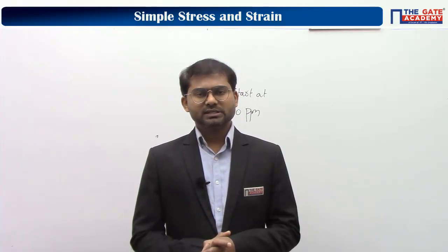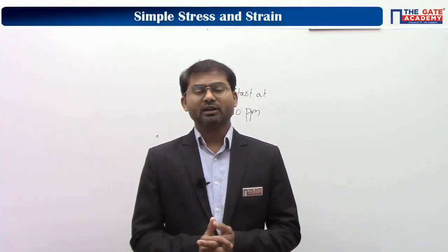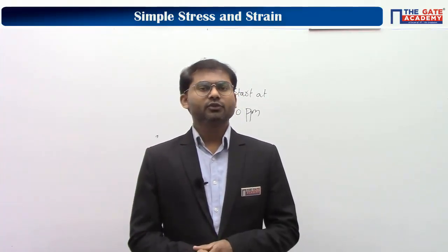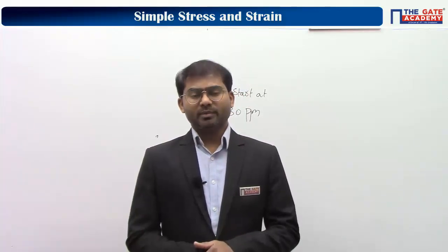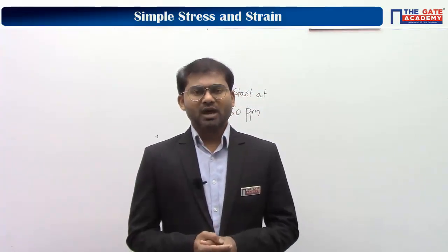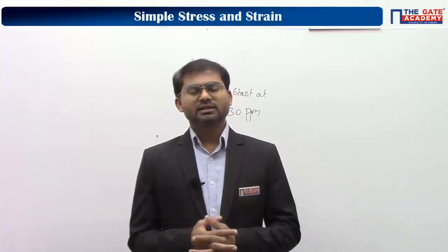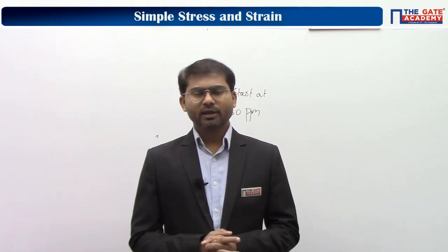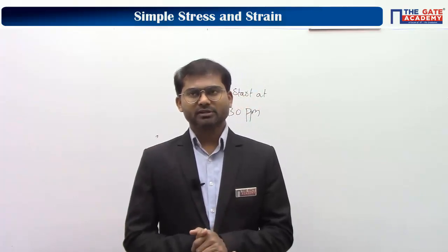Clear? So this is used in manufacturing metal forming operations, because if you do plastic deformation by metal forming operations, we are increasing its yield point. At a microstructure level, what is happening is the defects are getting closed up, and that is giving rise to the increase of yield point. As far as our SOM subject is concerned, we are concerned only about the increased value of yield point. We are concerned about the output itself, not how it actually has happened. We'll study those things in the subject of metal science or manufacturing engineering.